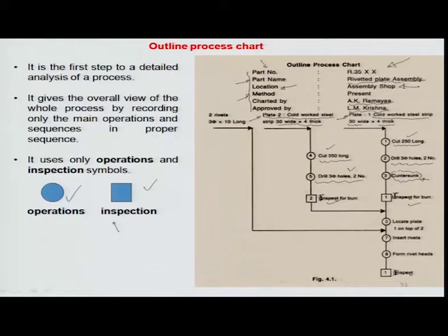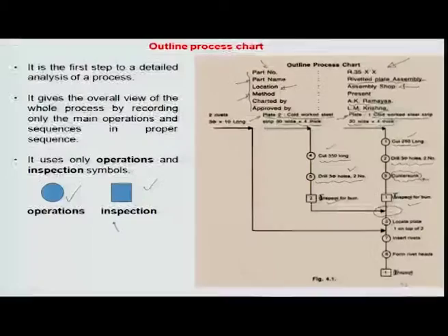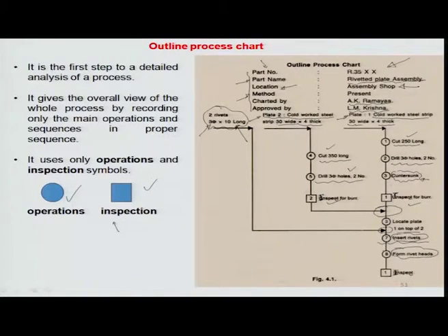And so, we are assembling plate 1 onto plate 2 at this point, where you are just overlapping them after inspection: plate 1, which is cut with two holes, both having a countersink profile, and plate 2, which is only drilled at concentric locations where rivets can be inserted. And the two rivets, in this case 3 mm in diameter, for example, and 10 mm long, are put together. So, the rivet comes in here and is inserted into the overlaying holes on the top sheet and the bottom sheet, and then we form the rivet head so that there is a lock on both sides, and then again an inspection happens.